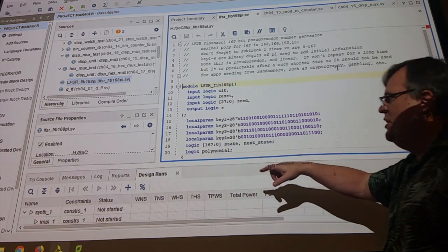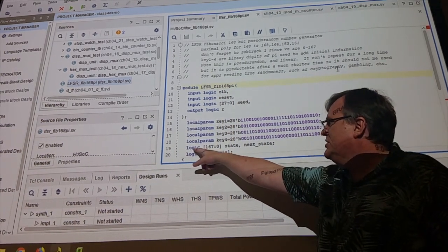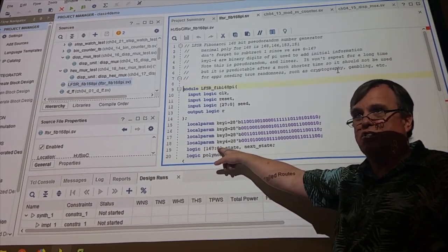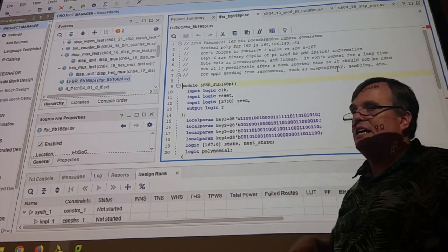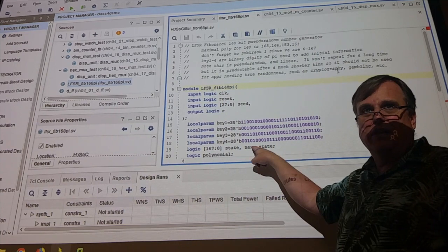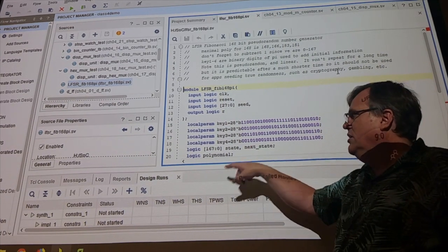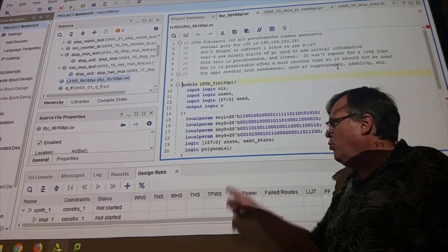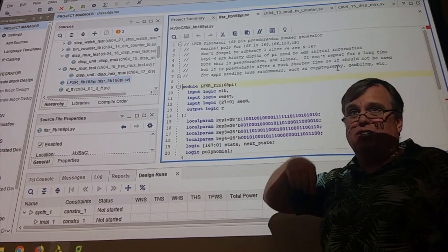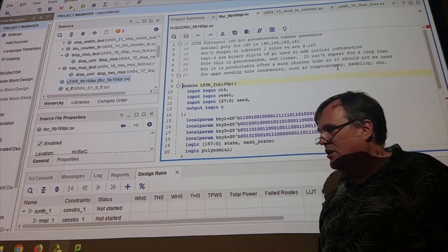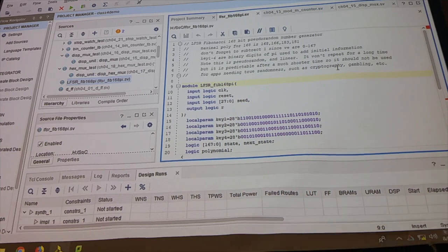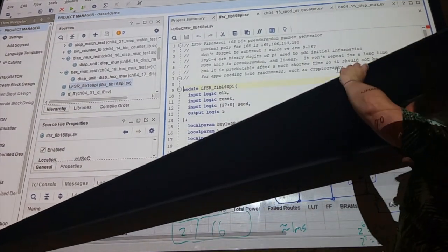All right. So then all I do is I set, this is where the key part comes in, right? Logic 167 to 0, so this is my 168-bit shift register, state and next state. All right? So this will be the register, this will be the combinational logic. I make a 1-bit thing polynomial. Technically speaking, those taps are actually a polynomial expression. So the mathematical formula for that, okay, I said I wasn't going to do this, but I lied. I do need one thing just to mention.